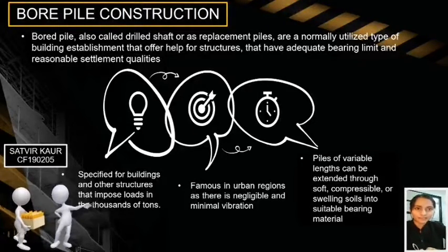Bore piles are specific for buildings or structures that impose loads in terms of thousands of tons. It is famous in urban areas because it is compact and also produces minimal vibration. The piles of variable length can be extended to suitable bearing material. Those are the specialties of bore pile.